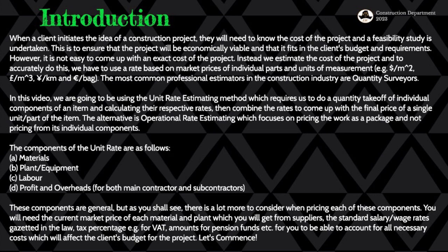Like let's say it can even be in terms of the units of measurement, like a square meter of a wall, maybe 230, 345, 115, or whatever type of wall you're looking at. You just look at a square meter, you price whatever materials are in that square meter according to standards. That's why we use rates, because the rate changes according to the different types of projects that you're dealing with.